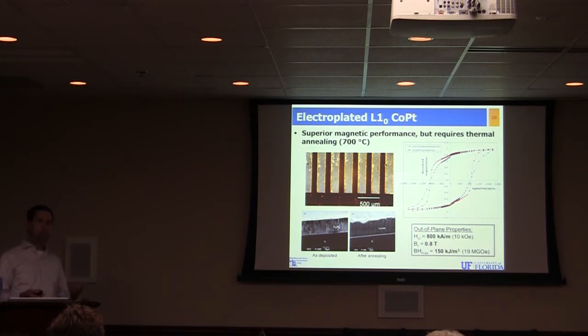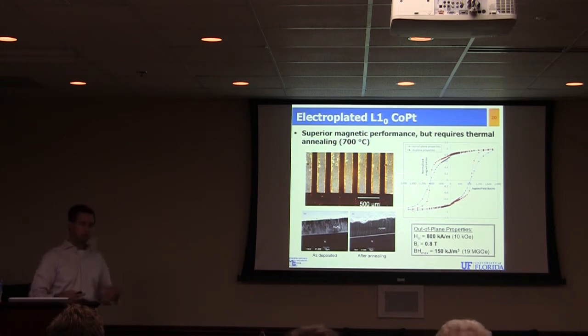So if we want to just simply measure the material properties, we sweep the magnetic field up to a large positive field, so we go up to here, and then we do a negative field, and then back to a positive field. That traces out that whole loop. If we're just in the business of batch fabricating the magnets, we don't have to do that. We just do a single blast to a high positive field and pull them out.